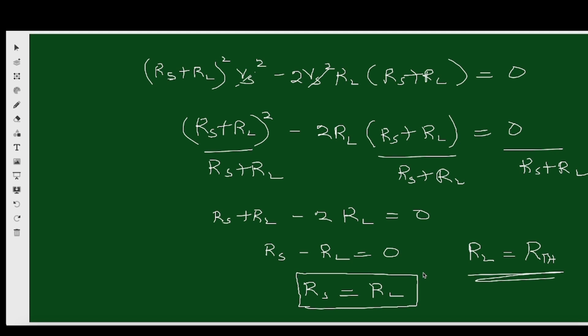Listen to me again. If the load is sized such that its Thevenin resistance is equal to the Thevenin resistance of the network to which it is connected, it will receive maximum power from that network. Any change to the load resistance will reduce the power delivered to the load. However, consider just the Thevenin equivalent of the network itself. We draw maximum possible power from the voltage source by drawing the maximum possible current, which is achieved by shorting the network terminals. In this extreme example, we deliver zero power to the load.